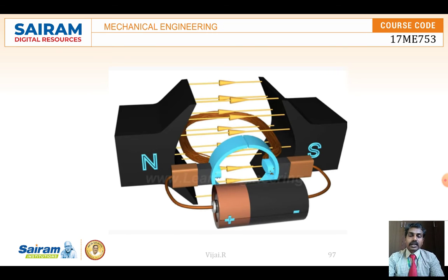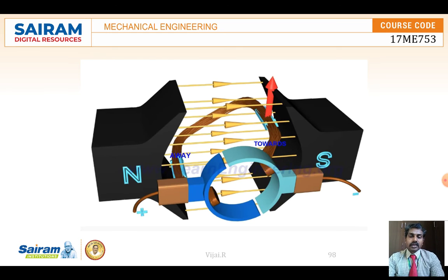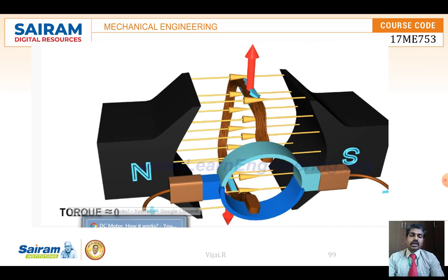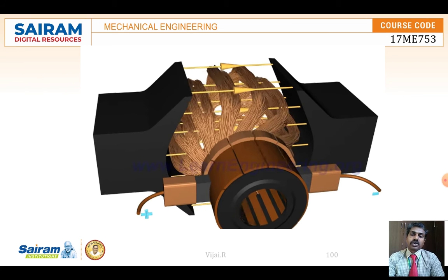When the coil is rotating towards and away from the magnetic field and comes to the perpendicular position, the magnetic effect is affected and the rotation will be very slow. On a particular side we can see that it will be zero. To avoid this, a number of coils are connected. Obviously, one by one they are going to produce the current, and many commutator segments will be there.